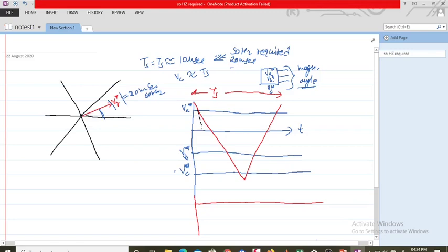Then you can say this value is here, and the switching signal S1 should be like this. Let's say you apply a condition that whenever the carrier signal is more than this, the switching pulse output is 0, otherwise 1.